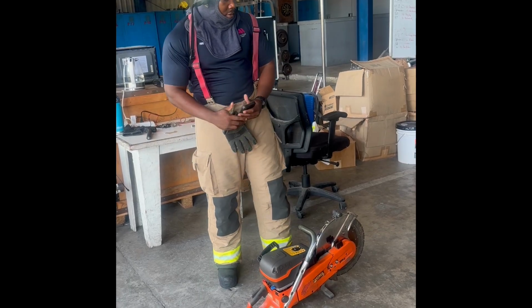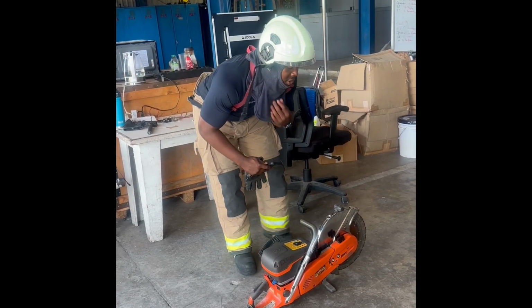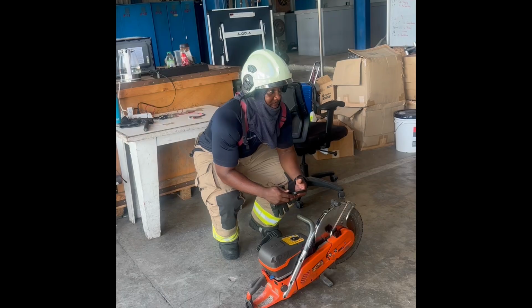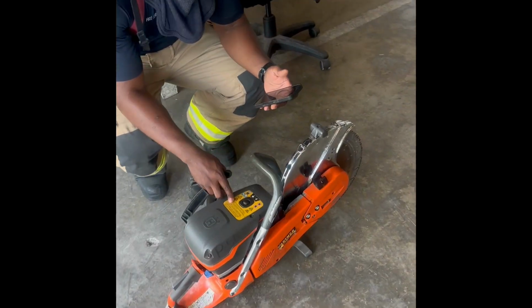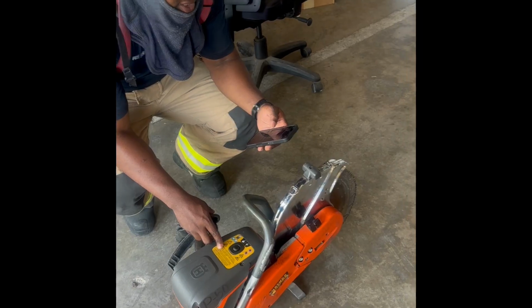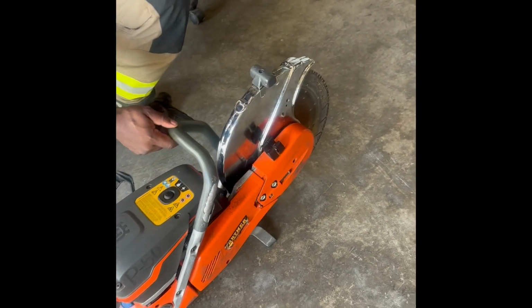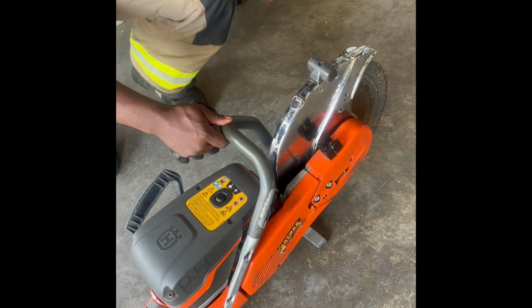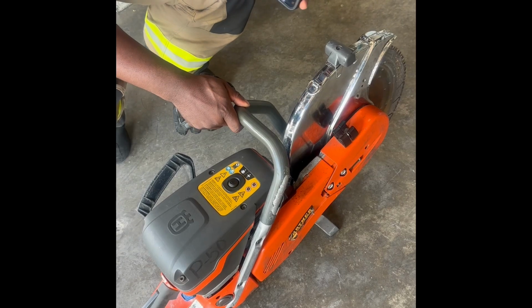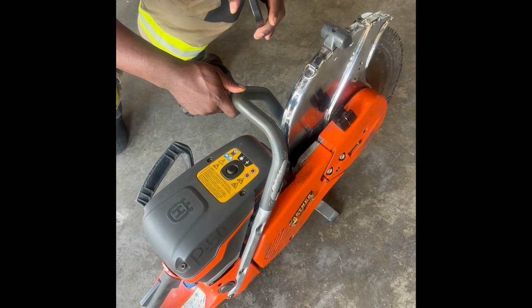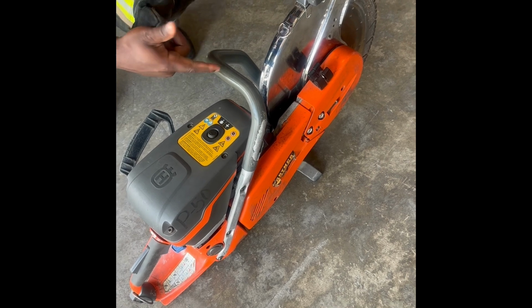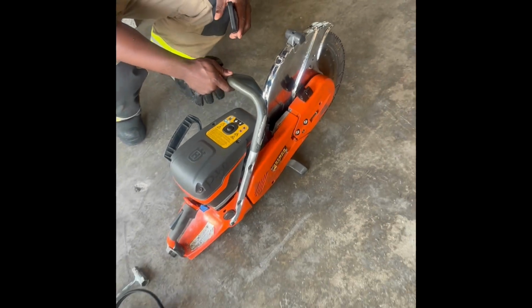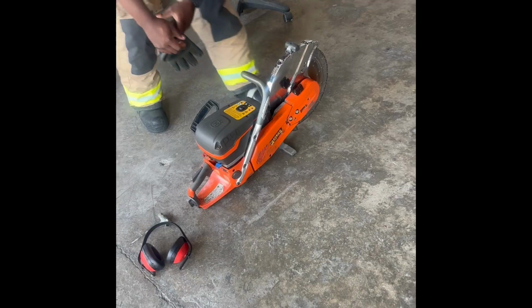Before using it, you also want to make sure that the blade is tightened. No cracks, no breaks, no missing segments. Make sure that it is not broken or unbalanced when using it. So there are types of inspection checks: we have the daily, the weekly, and the monthly. The difference in the checks can be seen in the weekly. Let me go through each now.